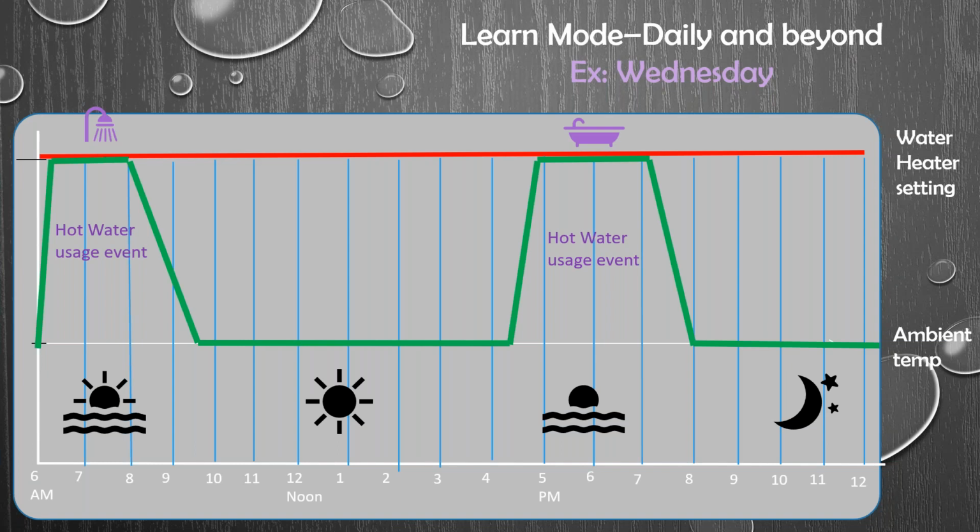You never know when the usage patterns are going to be in a hotel area. So you have that hot water circ pump, not necessarily 24 hours a day, 5 on, 10 off. Cut that power load way down low with the smart plug. So the smart plug is not necessarily for a small residential circulator. We could do up to a 6 amp load on there. So we can control larger circulators with it.